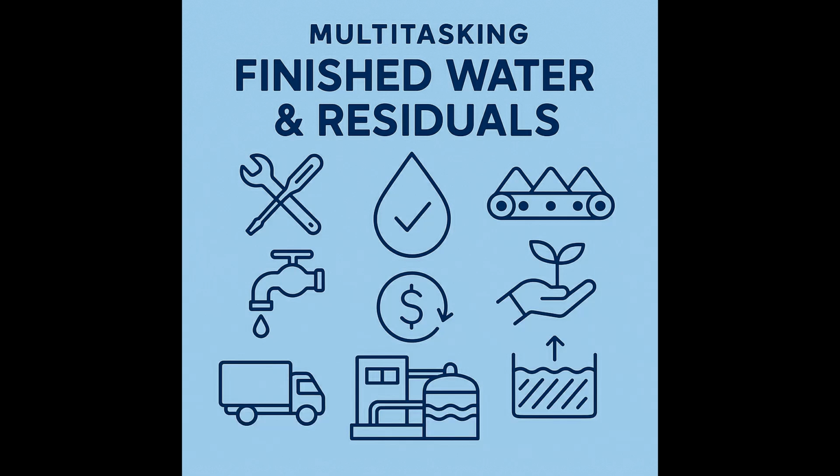So if a plant in Virginia, for example, wants to pursue or continue land application, what's the path forward look like, especially under VDEQ? The pathway is through that VPA permit. It involves detailed site assessments, nutrient management plans for the fields, establishing buffer zones, meeting limits for metals and other parameters in the residuals in soil, and rigorous record keeping. The specifics can vary, so plants must always adhere to their current active permit language, and they need to be proactively discussing PDS with VDEQ to understand current or anticipated requirements.